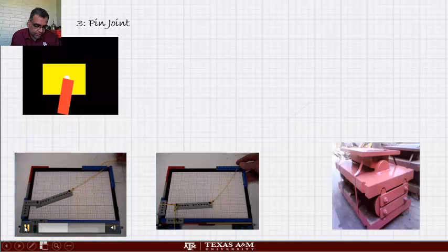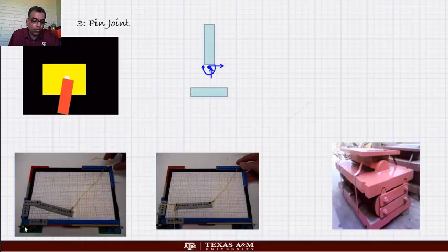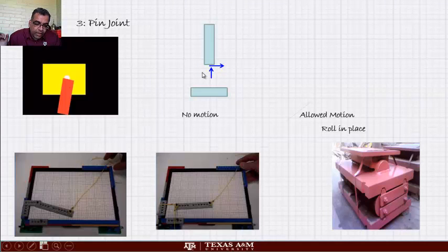So you can see that? Excellent. So now let us see what a pin joint looks like. If it did not allow any motion, we would have Fx, Fy, torque, right? But I want to allow rotation. So what happens is I will quietly remove the torque. If I am not able to supply the torque, it will be able to rotate. Now my free body diagram will look like this.